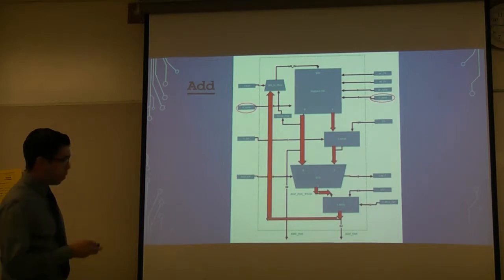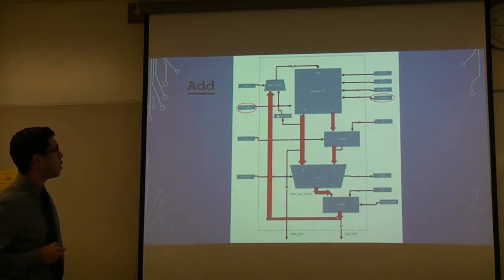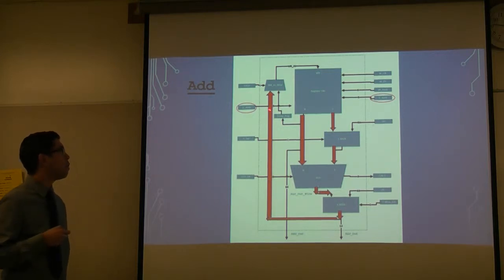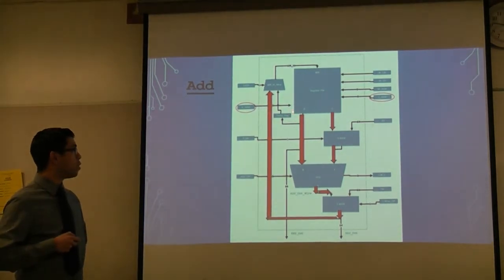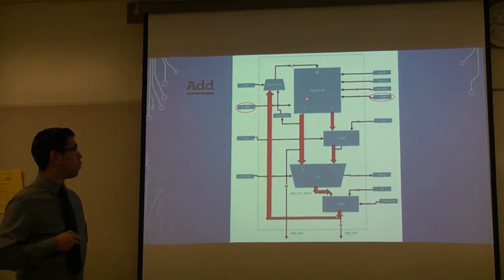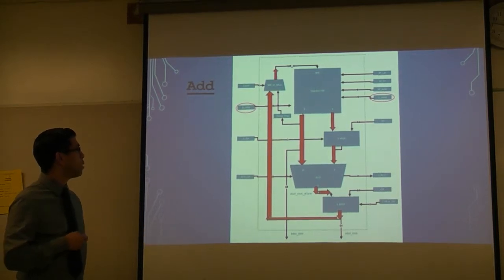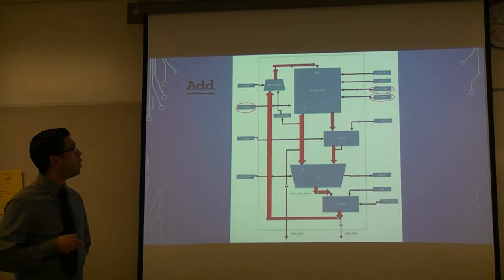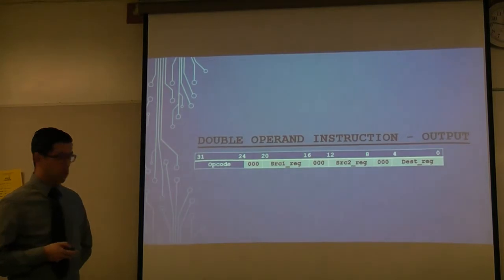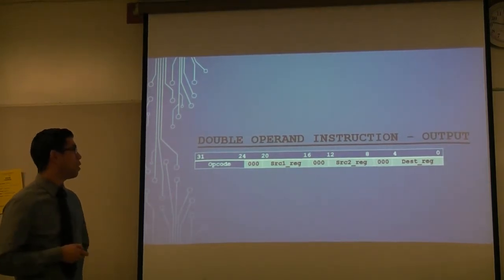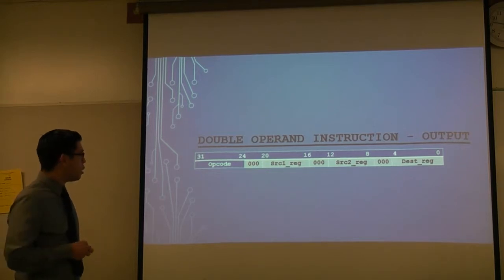Comes out here, out of the Y MUX. And we go into our Y, again, this MUX that we added in here was because of this register. This register gets written on every clock cycle, so the only time that it actually goes into the register file was when exchange is actually used. And that was for the exchange instructions, so we can just swap them over. Or we can hold this register with whatever we're writing for that. Here we're not using it, but we do go through that MUX, with the data from Y MUX. And then based on the W address, which is the write address, we wrote it into the register file.